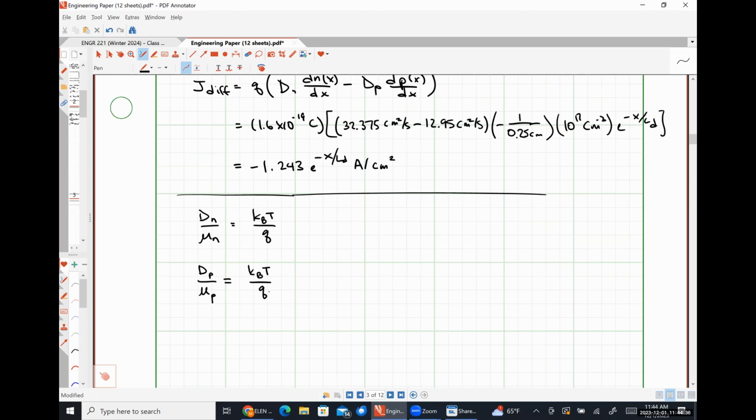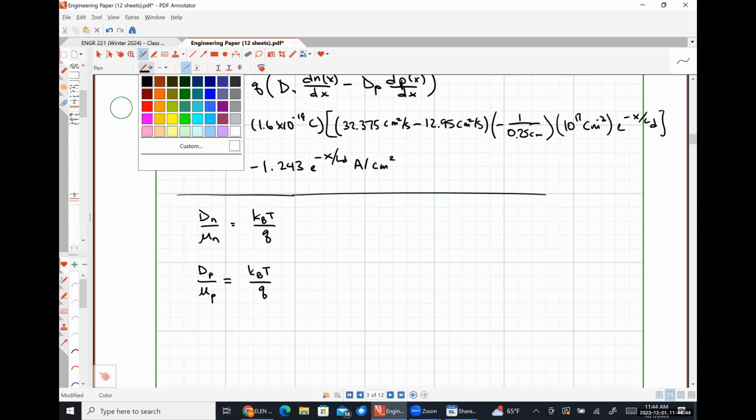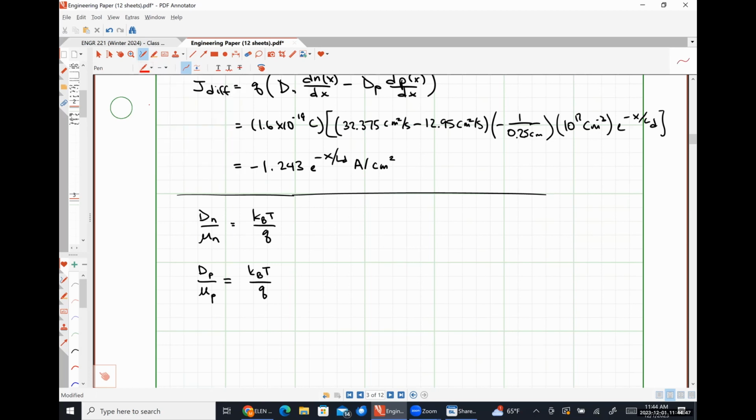And I have a note here that's effectively telling me that I made a small mistake in our last lecture, so let's go ahead and rectify this. In Wednesday's lecture, I erroneously said that kBT was approximately equal to 26 millivolts, and that's not correct. kBT over Q is. So kBT over Q is our thermal voltage, and that's the thing that we're going to wind up seeing most of the time anyway. So I apologize for that mistake. It's been 2 years since I taught this.